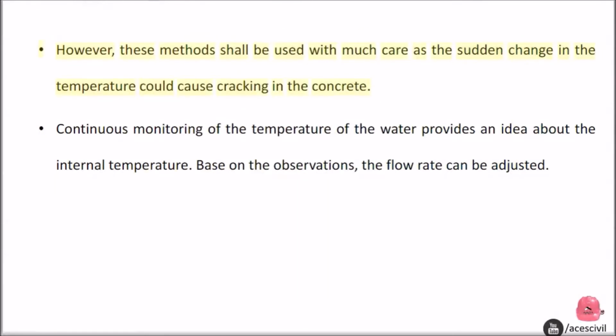However, this method shall be used with much care, as a sudden change in temperature could cause cracking in the concrete. Continuous monitoring of the temperature of the water provides an idea about the internal temperature. Based on the observations, the flow rate can be adjusted.